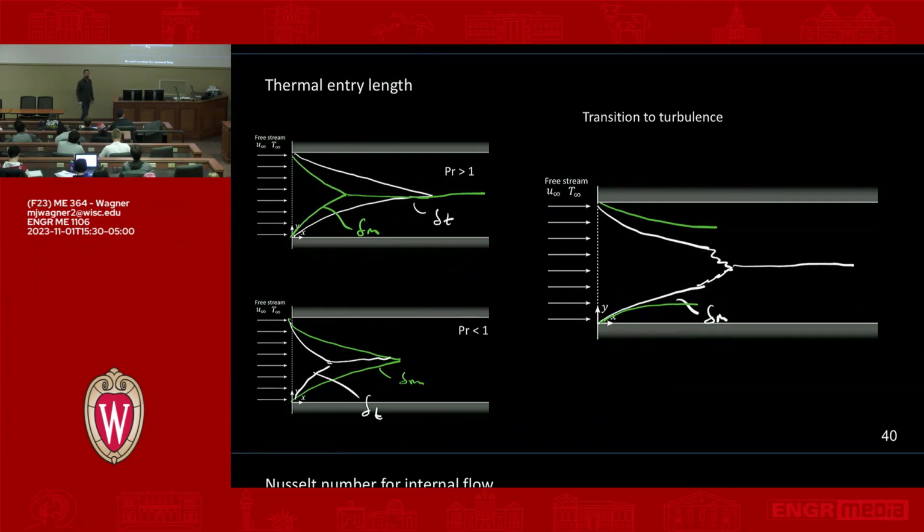Yeah, question. Is all the heat transfer through the viscous sublayer, or all the difference in temperature? Yeah, so the difference in temperature, the difference in velocity profile, is primarily in the viscous sublayer. And the viscous sublayer is dominated by momentum considerations, not thermal considerations, right? But once you get past the viscous sublayer, there's this eddy region. So the main mode of heat transfer and mass transfer, or momentum transfer, in the eddy region is the eddies, right? The bulk movement of the fluid.